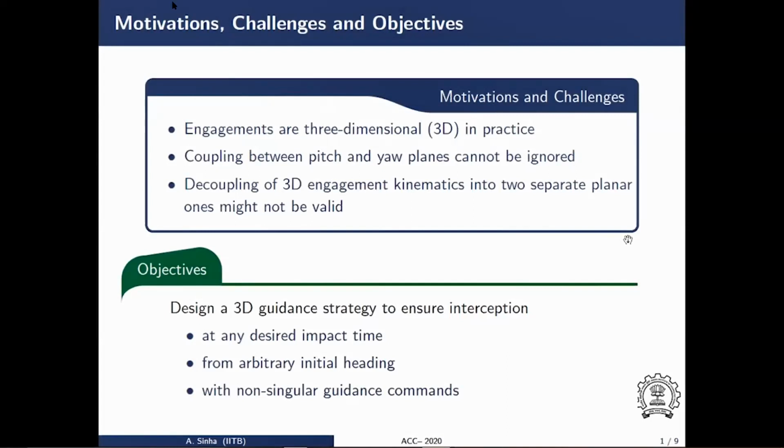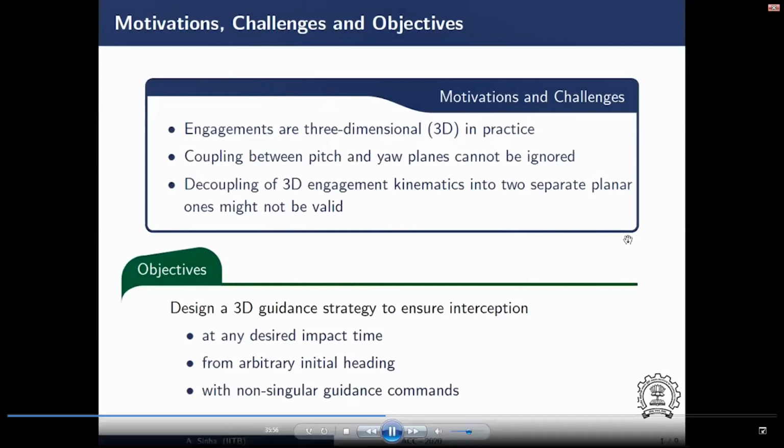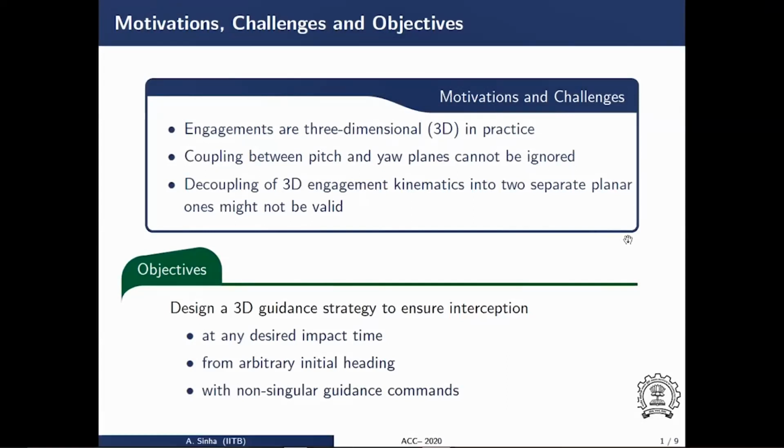So designing an accurate time-constrained 3D guidance is a formidable challenge, and the strategy must ensure a time-constrained interception at any desired time, irrespective of the engagement geometry. Also, it is quite important that the guidance commands do not introduce any singularity in the system.